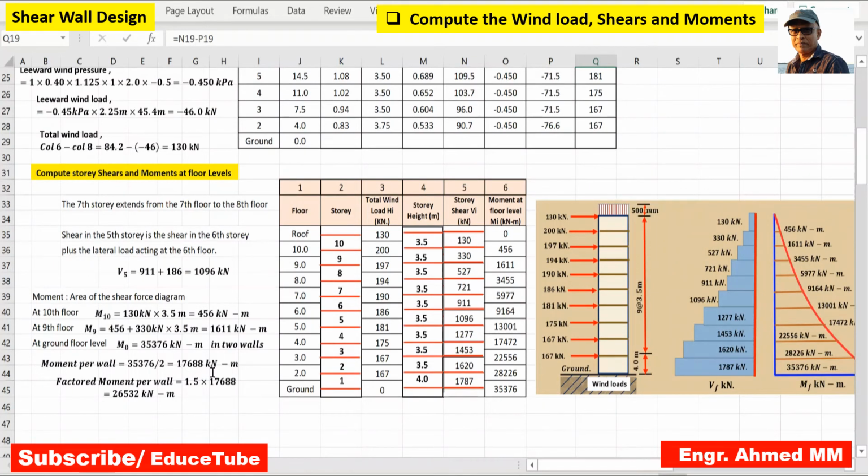17,688 kilonewton. So factored moment per wall, is it factored? Then we are multiplying it by 1.5. So this multiplied by this, it will be 26532 kilonewton meter moment on each wall. That's why I wrote here per wall. Here I have shown it.